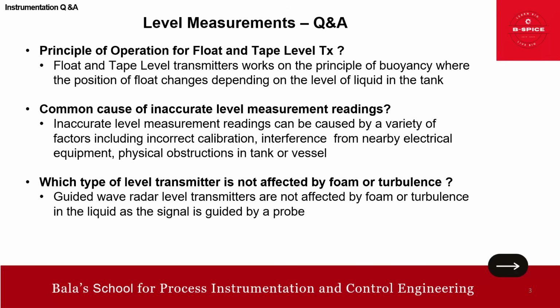Which type of level transmitter is not affected by foam or turbulence? Guided wave radar transmitters are not affected by foam or turbulence in the liquid, as the signal is guided by the probe. That is the beauty. So guided wave is one of the very good measurements. Of course, in guided wave also, if there is a lot of turbulence, we can have a stilling well chamber kind of arrangement, which I already explained in my video.